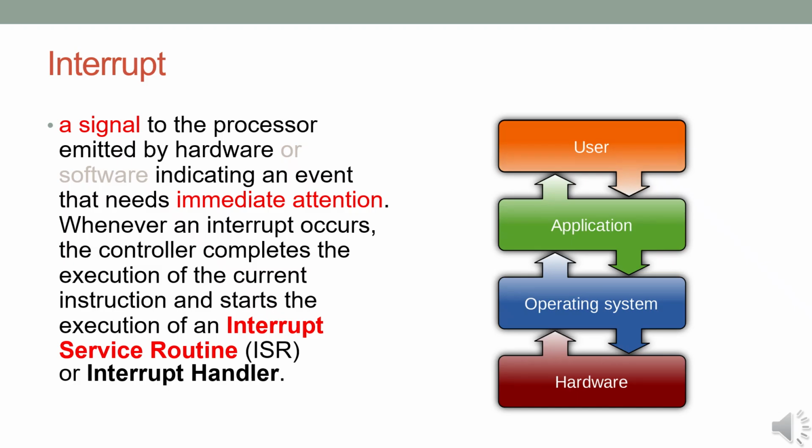If the button is not pressed, no interrupt occurs, and the microcontroller continues with its usual tasks. As soon as the button is pressed, the system detects the signal change and executes the assigned ISR. In our case, the ISR simply prints "hello." Once this task is completed, the microcontroller resumes its previous task exactly where it left off.